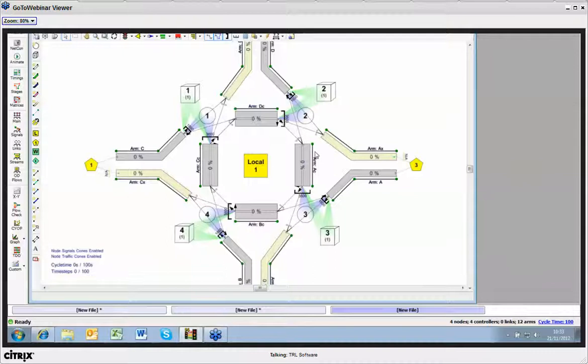The platoon dispersion model, the traditional one, is more suitable where you've got stop lines that are further apart, and as you want to model traffic leaving one stop line and then arriving at the next stop line, you want to get that offset timing spot on. That doesn't happen on closely spaced stop lines to a great degree anyway, so that's why the CTM model has taken that aspect of it out and focused on the blocking back.